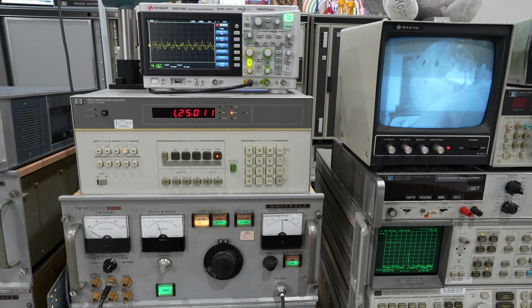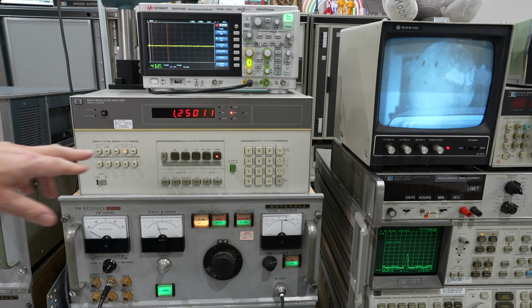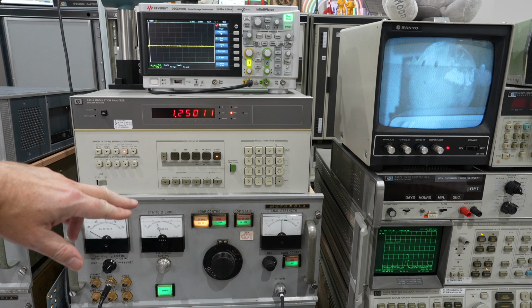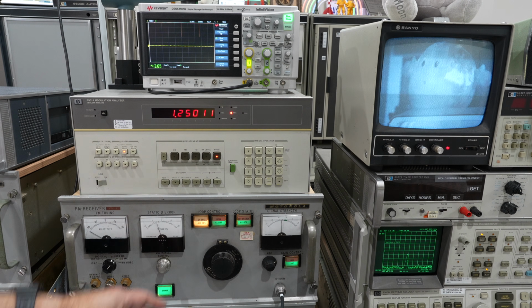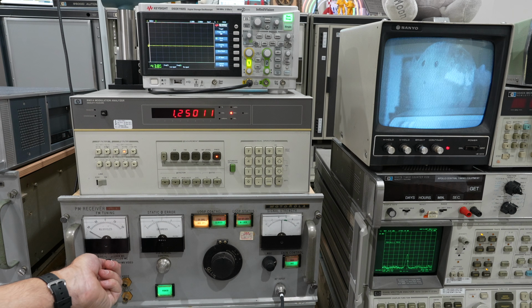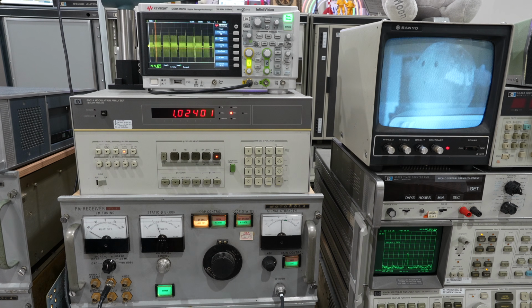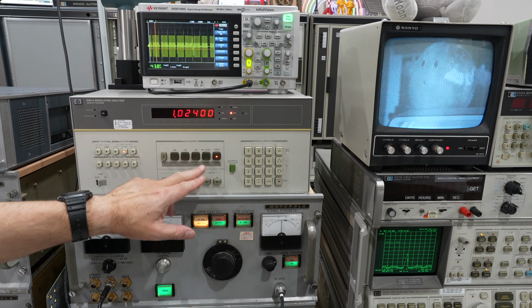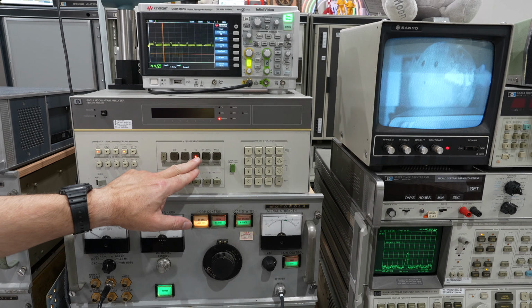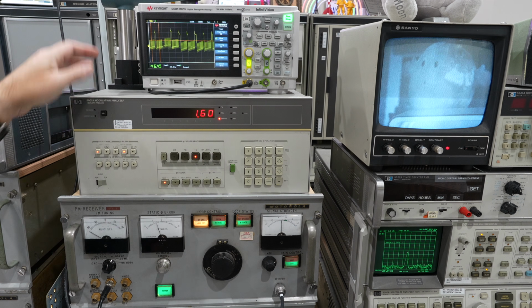Alright, so on the decoding, I've got good news and bad news. So right now, I am decoding voice. I am on 1.25 MHz. Say something, Mike? 1.25 megahertz. Alright. Now I change it down here to 1.024 MHz. And got it. It got my bits, but they are decoded in FM, and what I want is phase modulation. And if I do phase modulation, I got some bits, but not everything I want.